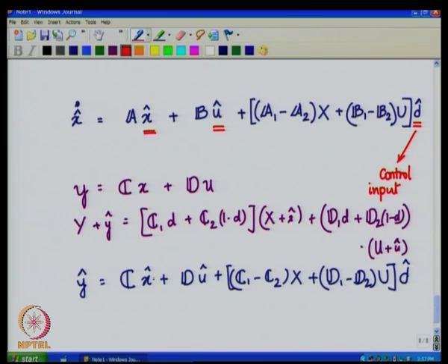Observe again the same form, you have the small signal terms coming in, and this is the dynamics of the state matrices A and B. They do not contain any small signal varying term. At most they would contain only the steady state terms, which for a given operating point is constant and fixed, and therefore they can be used for controller design in the linear time invariant mode itself.